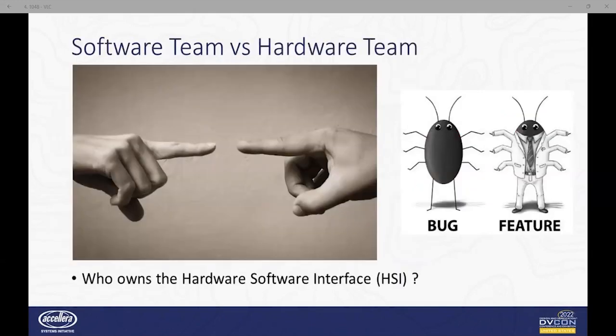Emulation tests the integration of software and hardware. It covers hardware features that are hard to simulate, like the test that takes way too long to run in simulator. Emulation is supposed to catch system bugs. If you keep seeing software bugs that should be caught by unit tests, or RTL bugs that should be caught by simulations, you have a much deeper problem.